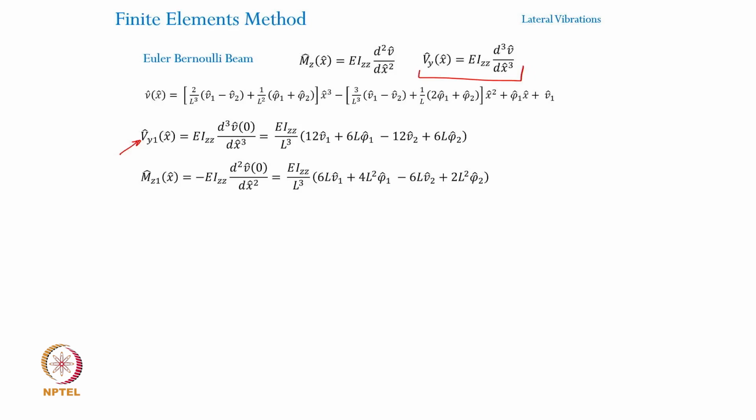gives us the shear force at the left node position, and by using this particular interpolation function in the expression here and then taking the derivative, you can finally get an expression relating Vy1 cap in terms of all the four nodal displacements.